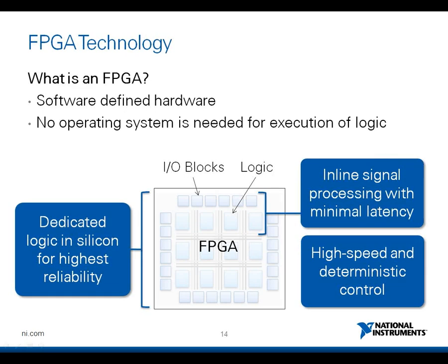Now, let's just talk about why we're here today. That's FPGA technology. So I guess the first question would be, what is FPGA? FPGAs are field-programmable gate arrays, essentially a silicon chip with unconnected logic gates. You can define the functionality of the FPGA by using software to configure the FPGA gates. There is no operating system needed. So essentially, your logic executes only in hardware. This is going to give you extremely high reliability in terms of application development.